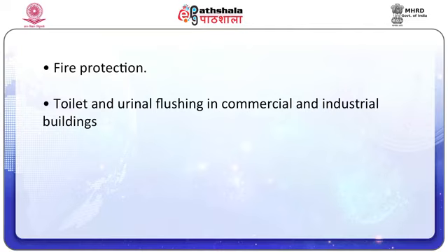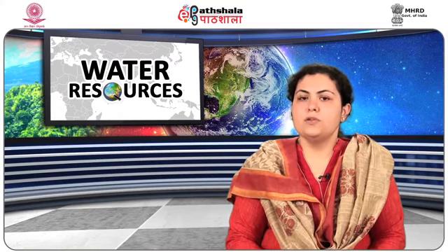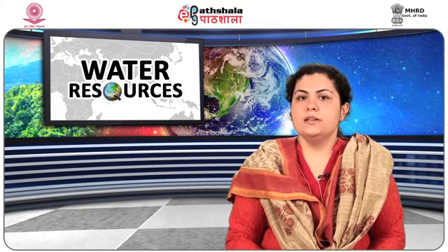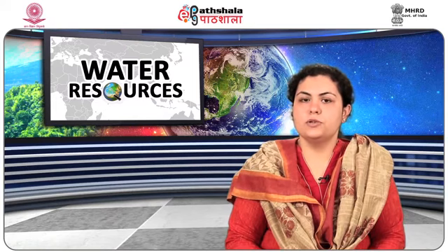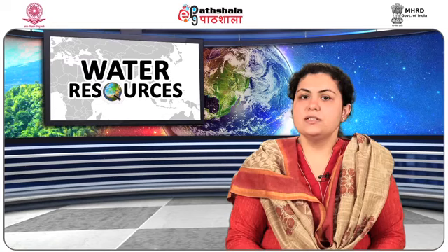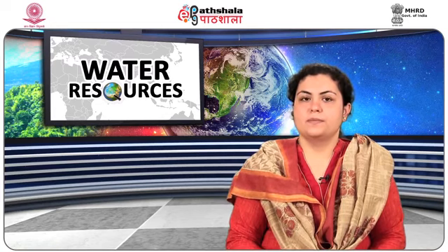Fire protection, toilet and urinal flushing in commercial and industrial buildings. The disadvantages of urban non-potable reuse are usually related to the high costs involved in the construction of dual water distribution networks, operational difficulties, and the risk of cross-connection.